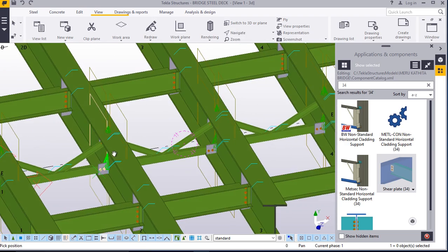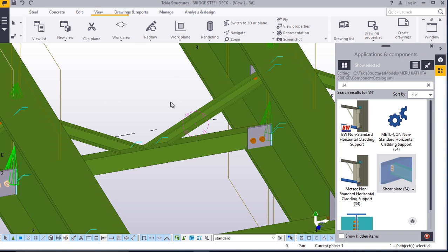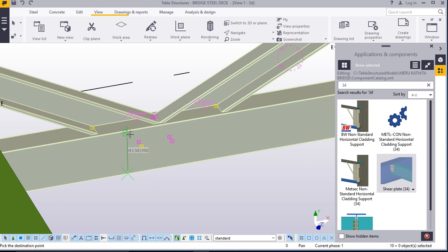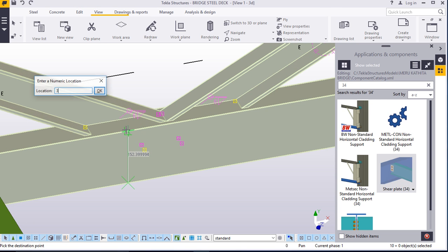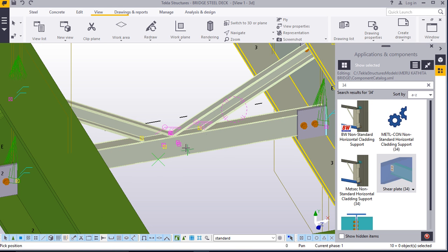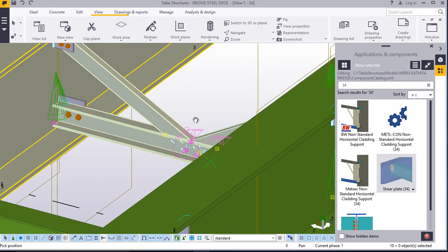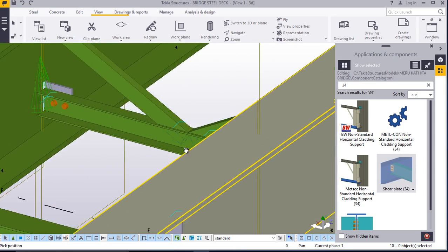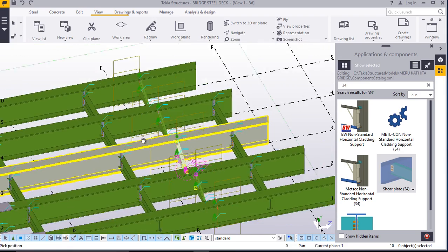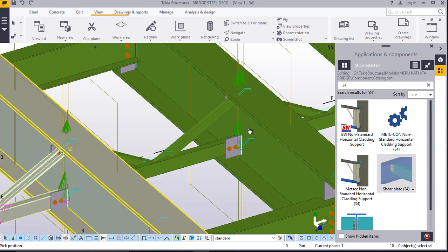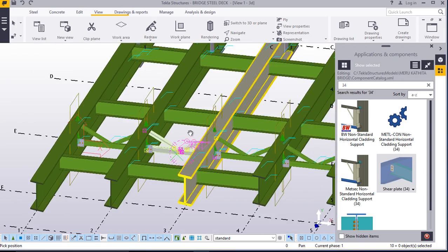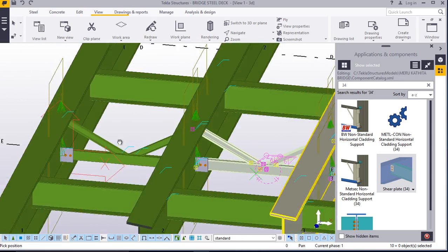Come here and bring this up slightly by 30. Click that, snap down here and snap up here, enter 30 and enter. Navigate, rotate this. Just check on all bracings whether the connection to the main girder is properly linked up. Very important. Now everything is good.